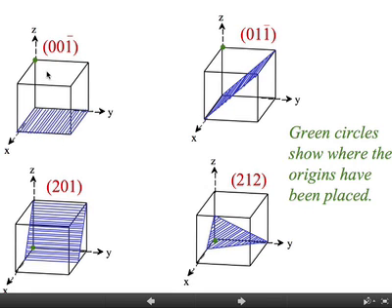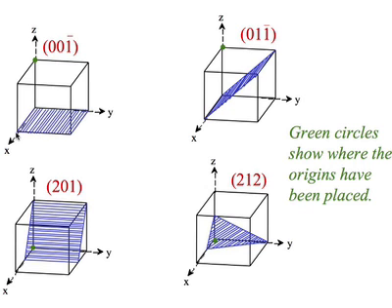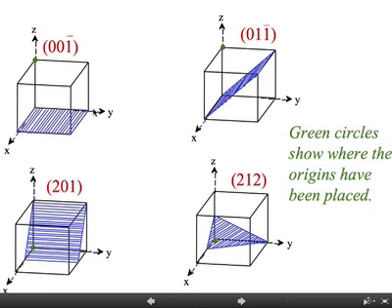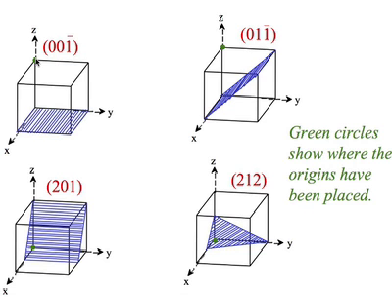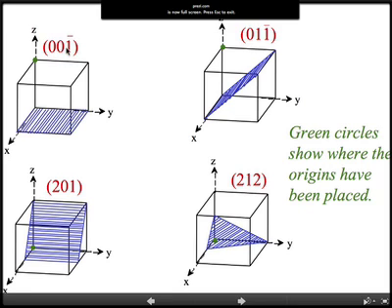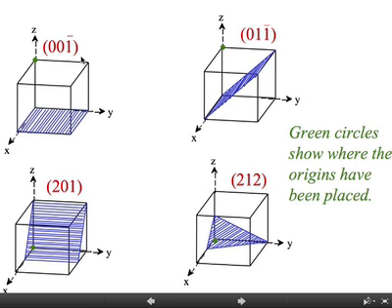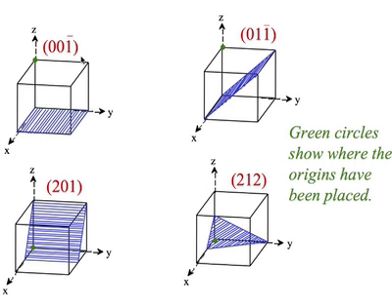Let's see where the negative comes from. You can't really tell, but in X there is no intersection, right? It's parallel to X. And in Y also there is no intersection. It's parallel to Y. You see that? So 0, 0. But in Z, it's at the bottom. The green is now the origin, so it's underneath the origin, so it's -1. When you have a minus sign, it's placed on top of the number, as shown here. So you have 1 over infinity, 1 over infinity, and 1 over -1, and the minus goes on the top. Again, just a formality. So that should be clear. And the other part, again, you can work it out. Not that difficult.